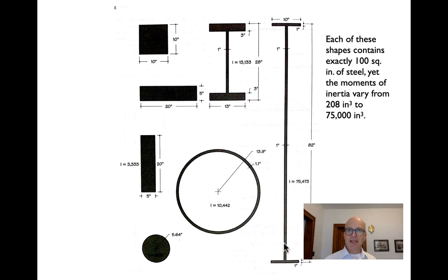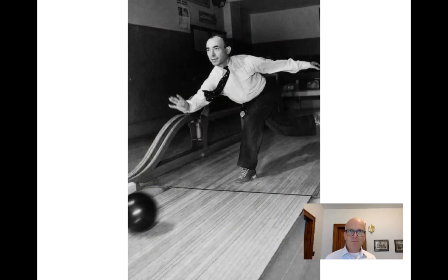And this explains why when we're dealing with steel construction especially, you see I-beams everywhere, because those flanges and the depth are exponentially more effective at carrying a bending load. Who else is interested in moments of inertia?